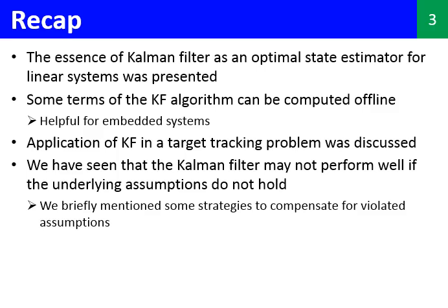In the previous lecture, we identified the Kalman filter as the optimal state estimator for linear Gaussian systems. So if we are to employ the Kalman filter in our application, we should make sure we have a linear Gaussian state transition, a linear Gaussian measurement model, and a Gaussian initial belief.